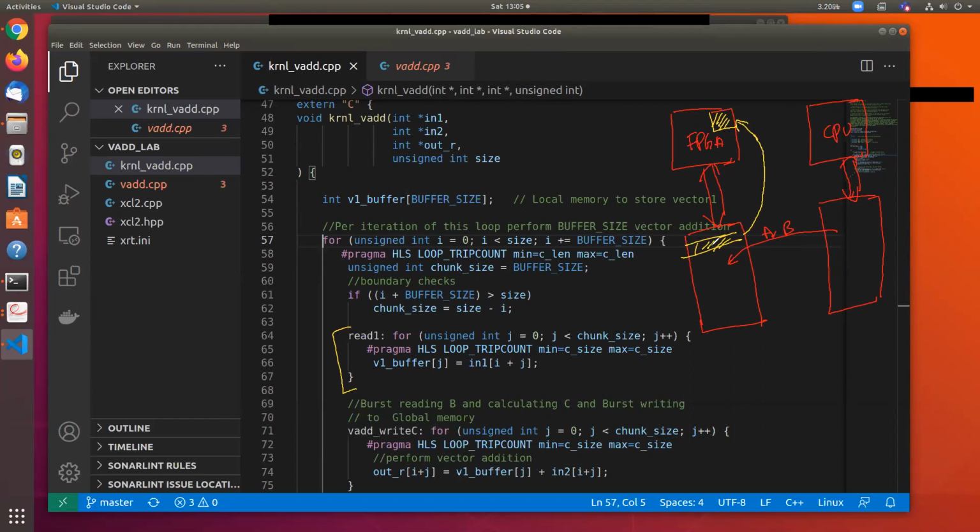In fact, the strategy when we design a system is this: here we are not seeing much benefit, but the key mantra you have to remember is maximize data reuse. Data not use, data reuse. Once we bring data to the FPGA, we should use it as much as we can, because our goal is to minimize the main memory traffic to the DRAM.